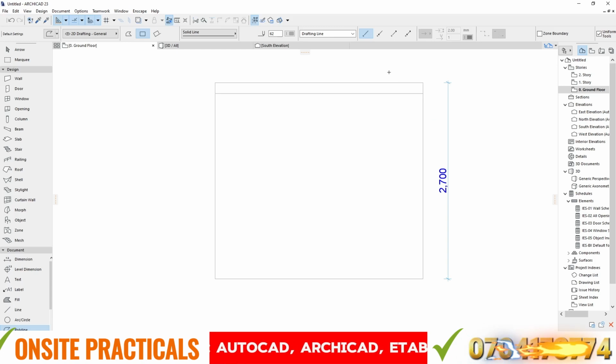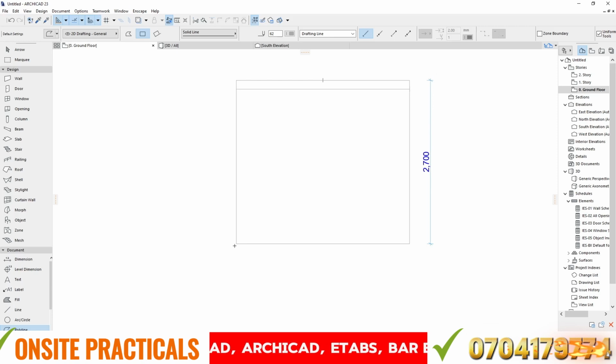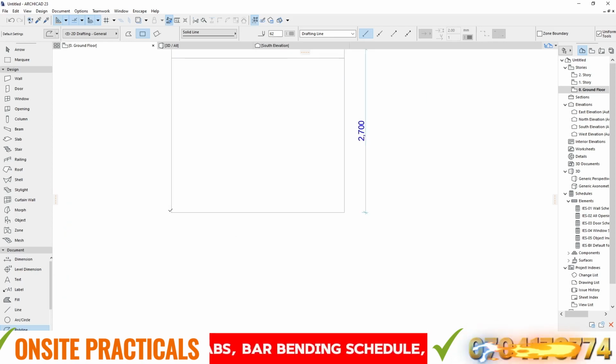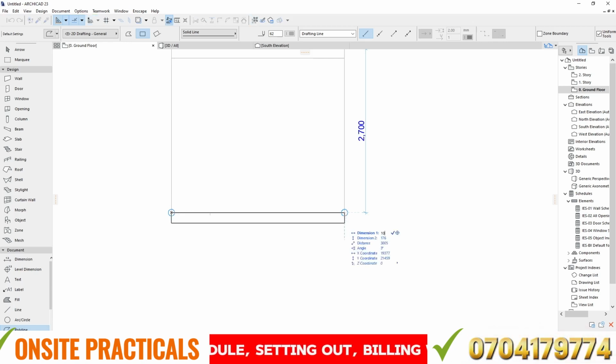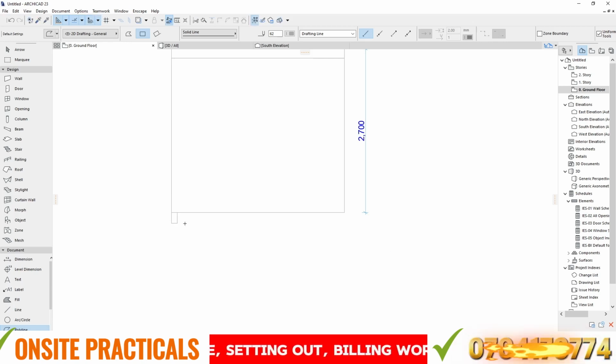So that then the floor will be at the top, so that then we can say that the floor to floor height will actually be 27, right? So that's the whole thing. Now, if I come here, for example, when you're doing the floor on the slab on grade, this is what exactly we call the slab on grade. The first slab that you're going to cast on the ground, right? It's actually going to form the ground floor slab. So when you are casting it, you will go downward, you see, because you're probably going to have like 100, maybe 4 inches thickness for that slab.